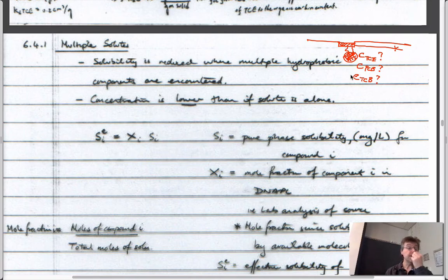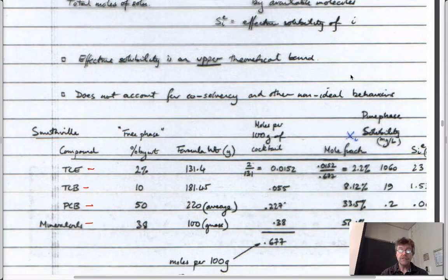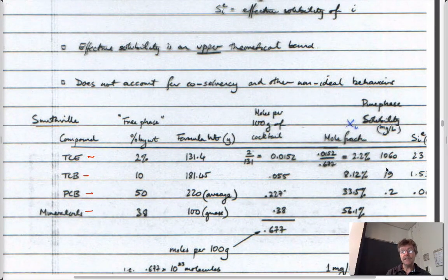And so, what are those concentrations? That's important because all of our calculations using these advection diffusion solutions rely on knowing the concentration upstream to be able to project what the concentration is downstream. So that's the first step. And so we know, for instance, that the solubility of TCE is something of the order of 1,000 milligrams per liter, 1,000 ppm. But if you put this in water, just like sorbing stuff onto solid, it has to compete for these solubility sites in the water as it's dissolved.